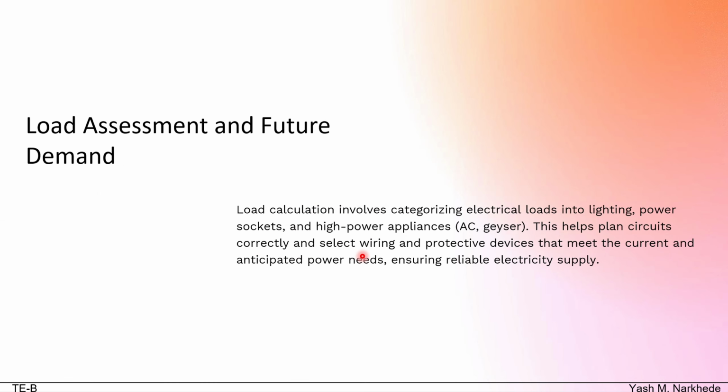So next is load assessment and future demand. Load assessment means identifying all electrical loads in the house, lighting, fans, sockets, and appliances. It helps decide the size of wires, fuse ratings, and the number of circuits. Planning for future appliances ensures the wiring can handle extra loads safely.